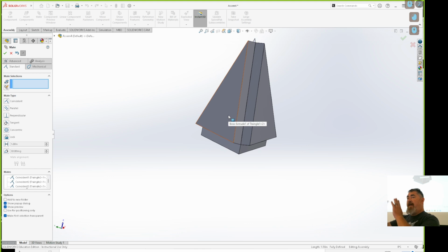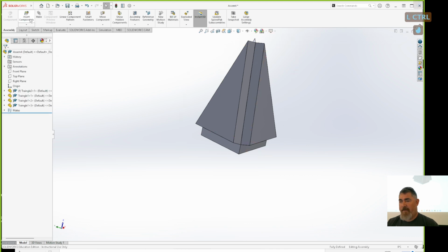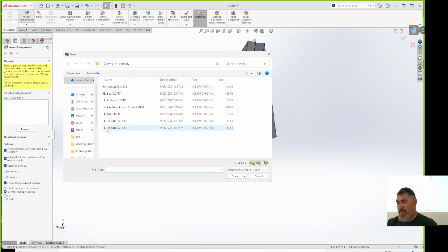And so, on an edge, you can see that it can slide back and forth and rotate around that edge. When you do faces, that face is basically stuck there, can't rotate up and down, or kind of stops rotation in two directions. But you can slide in two directions and rotate in one. On an edge, kind of the opposite. I'm going to just undo, or just add one of those back in, just so you can see what happens.